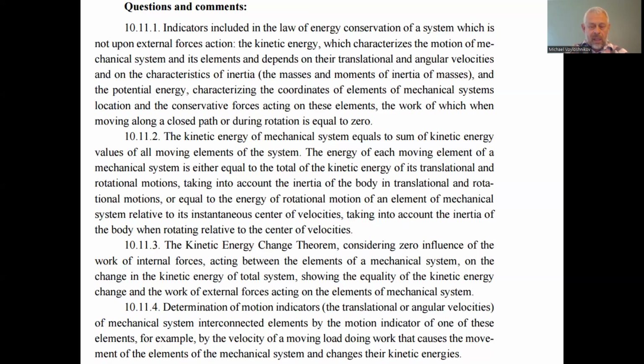The characteristics of inertia of the rotation in the second case will be other than in the first one. So in the second case, we have to consider the inertia of the rotation not relative to the center of the mass of the mechanical system, but relative to the instantaneous center of the velocity. And this characteristic of inertia for the rotation corresponds not only to the own characteristic of inertia of rotation relative to the center of the mass, but as well to the transfer characteristic of the inertia of rotation, assuming as well the rotation of the center of the mass relative to the instantaneous center of the velocity.